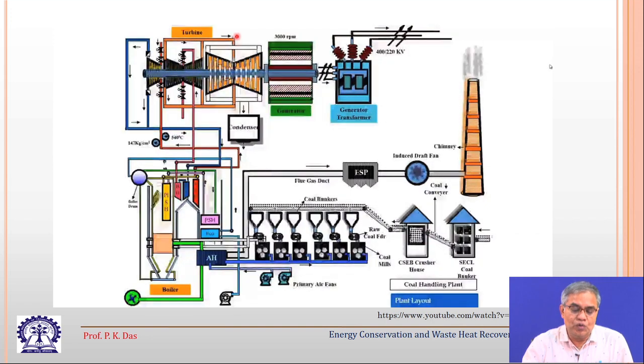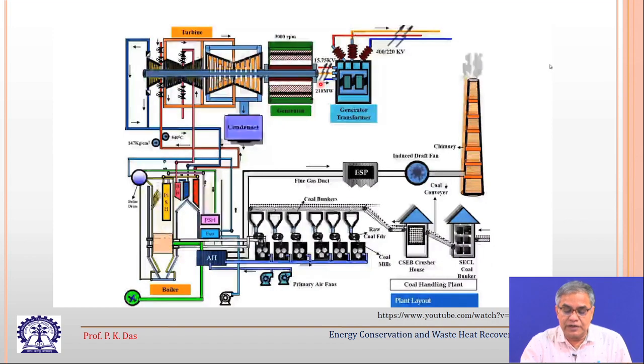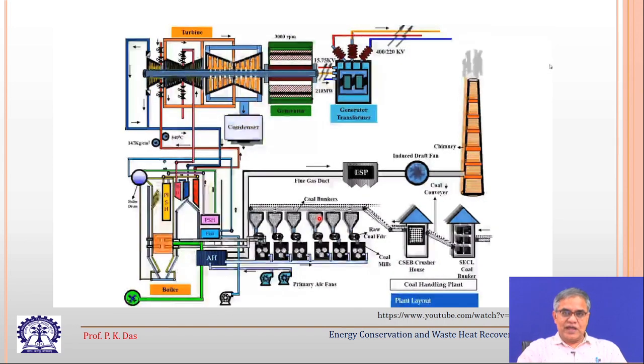Now it is going to the low pressure turbine, and from the low pressure turbine the steam will come to the condenser and it will condense. So, the water circuit is complete, and then there is some sort of alternator and a generator, etc. So, electricity will be generated. With this we are getting the water circuit, the steam circuit and also the air flow path.